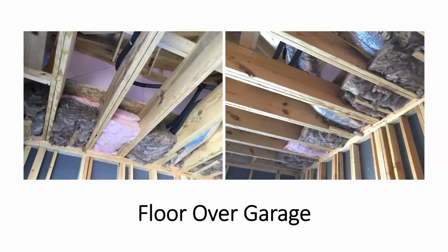I've put this in several of my webinars. The floor over garages. It's not necessarily a floor. It's an extension of the second floor that overhangs a little bit of the garage. Even though this looks decently insulated, it still needs blocking between all those floor joists, or in this case, the ceiling joists of the garage. It needs all those to be sealed at the end. It needs to have blocking there.